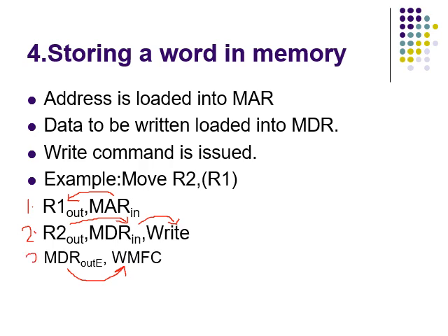I will repeat it. As in the case of the read operation, the write control signal causes the memory bus interface hardware to issue a write command signal on the memory bus. The processor remains in step 3 until the memory operation is completed and the MFC response is received.